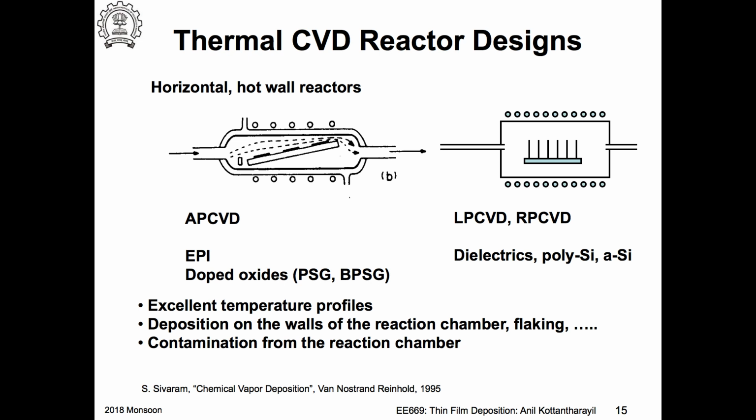So it would have started to crystallize, and there will be a mismatch with the deposited material because it's no more amorphous, and then there will be huge stress. So flakes of silicon nitride would start to fall off from the furnace. I then need to clean these tubes quite often. That is not going to be an easy task. I'll have to take this out. What is being done these days is that you pass through it some gas that would etch the deposited material.